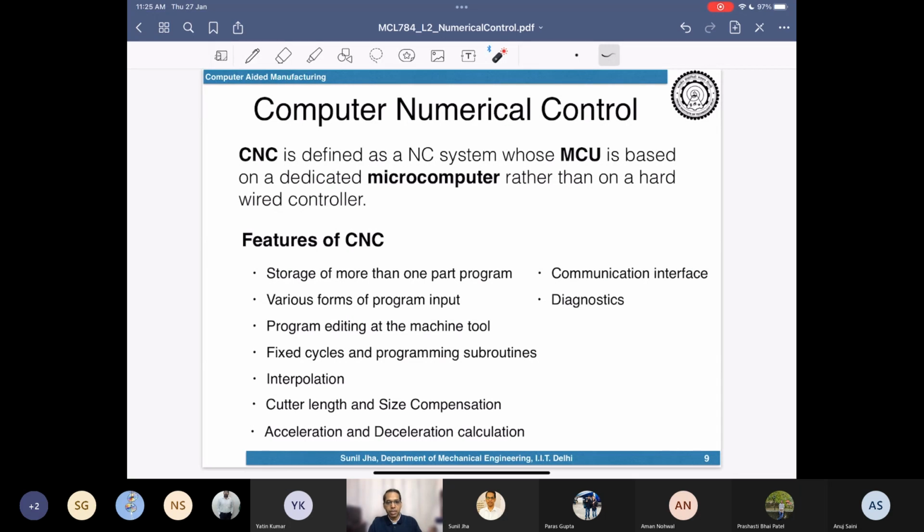Then you will get a lot of parameters, which you might not have realized, for how the machine health will be monitored. I will certainly discuss that when we discuss smart manufacturing, because we are doing one project where we are interfacing with the CNC milling machine in the workshop and bringing all the data into the lab to understand it. This machine controller will keep giving you a large amount of data, so that you can understand the behavior and health of the machine, and the operations, basically whether the machine is achieving the precision you have defined or not.